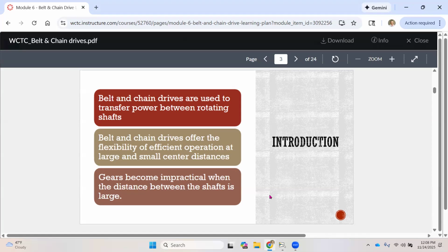When we have a belt or a chain drive, it's more flexible because now we can move that center distance for whatever size belt or chain that we have. So it becomes a lot more flexible. So if we do need center distances to be further apart than items right up against each other like gears, belts and chain drives can be a good application for that.